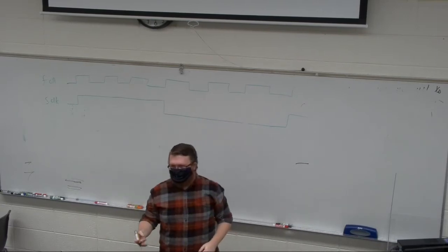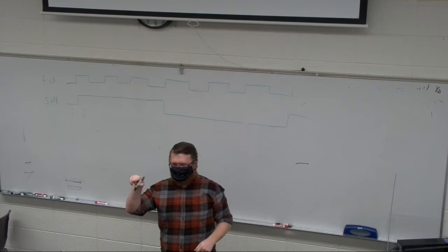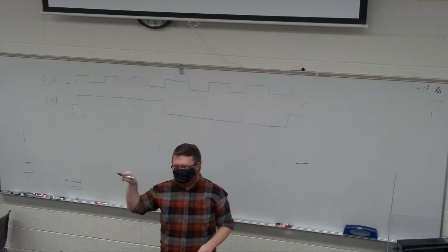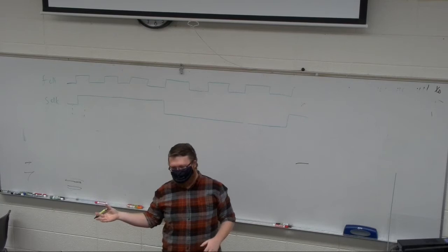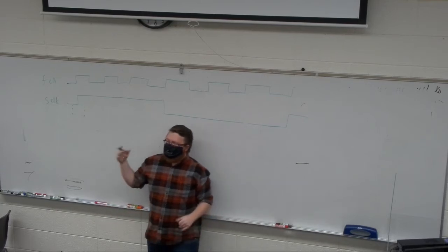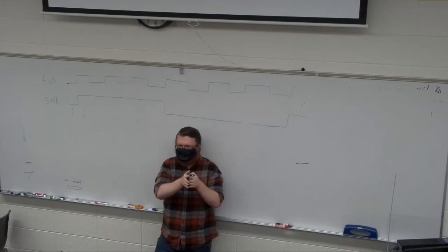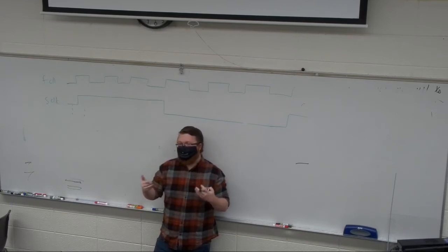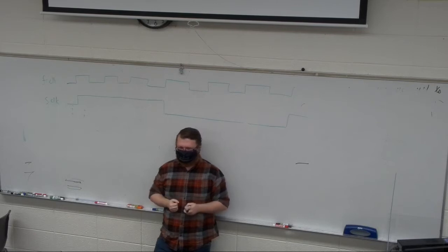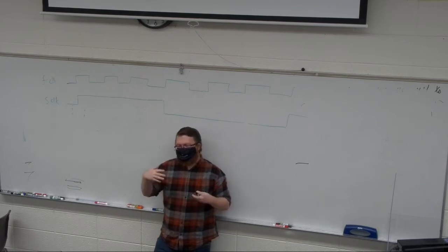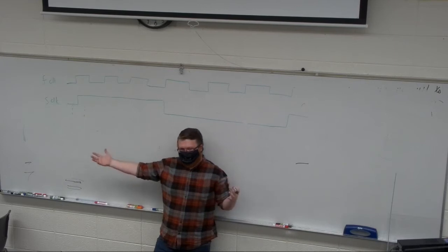So if we have 1% drift, well, we only have half of it, right? So if we have 1% drift per clock, so if we're off by 1% of the ideal, then we can take half of that, because we're centered and we can only go 50% one way, 50% the other way. And then we can subtract out the setup or hold time. And then you can calculate from there how many clocks before you start violating setup and hold times due to clock drift.